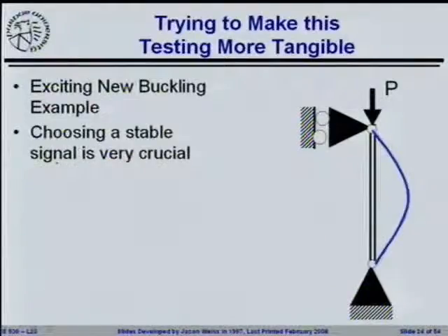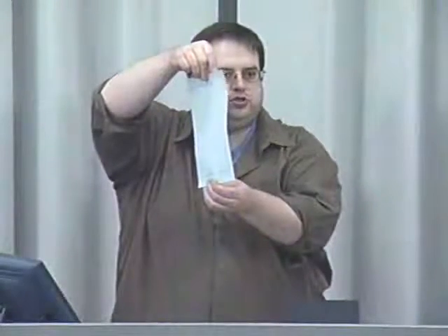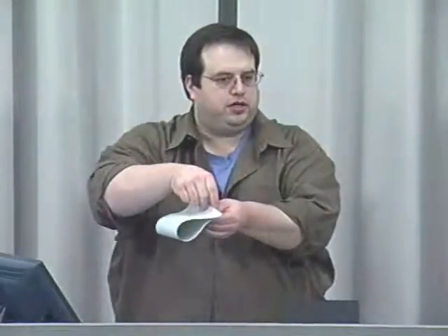If we wanted to take this into the next example, we could think about this in terms of the concept of buckling. If everybody took a ruler or some sort of a piece of balsa wood and you started to load up that ruler, and I think you all did this in a mechanics and materials type of class, you keep loading it. You've got a dowel rod, you stack weights on top of it, you keep loading it, and if it's in load control, as soon as you get over that critical value, you snap that piece of balsa wood. The whole thing comes down.